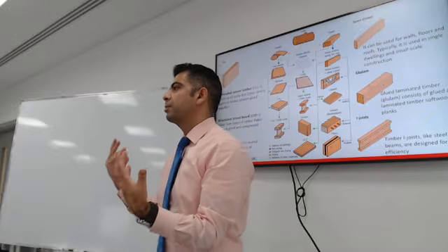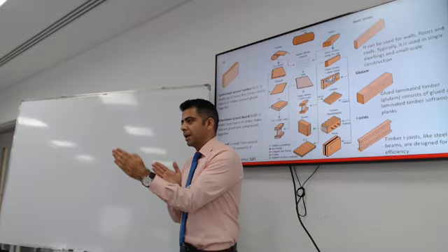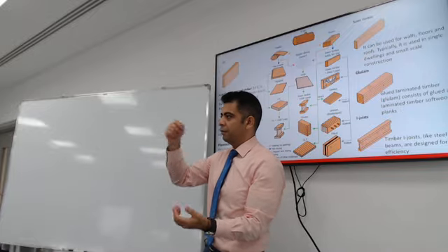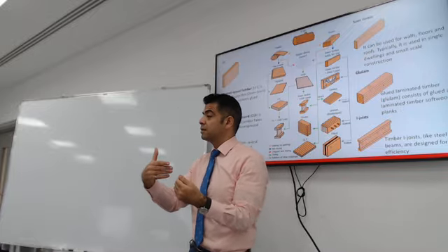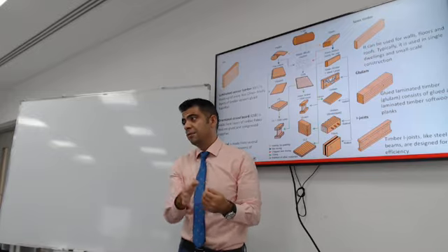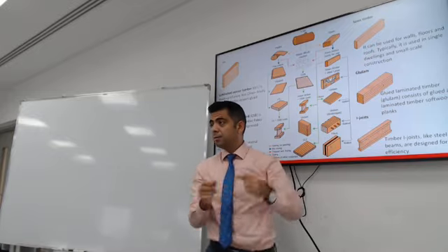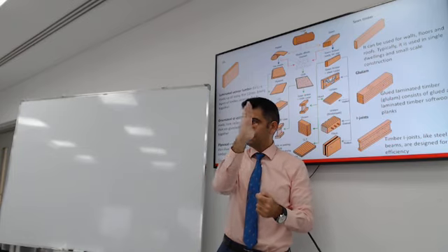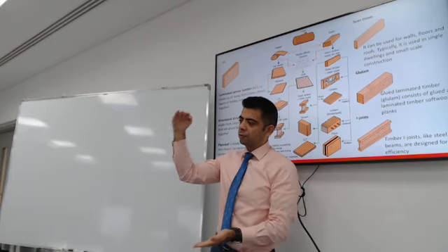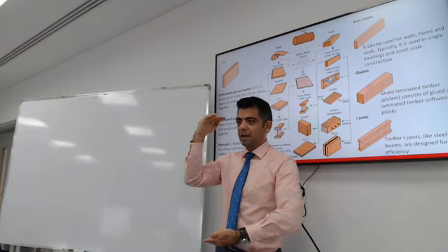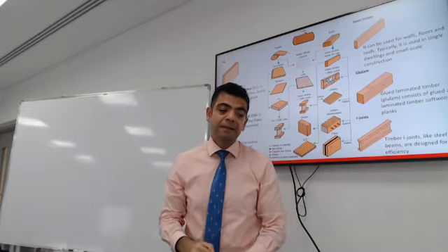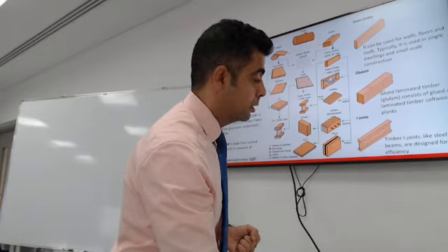I'll show you what a typical frame looks like. It will be like the joists, you put some plywood on it, and then finishes, and you create the wall the same way. You create studs from sawn timber, 14 inches on center. You put a top and bottom board, and then you build the next floor on top of it. I have a detail that shows you how to do that.